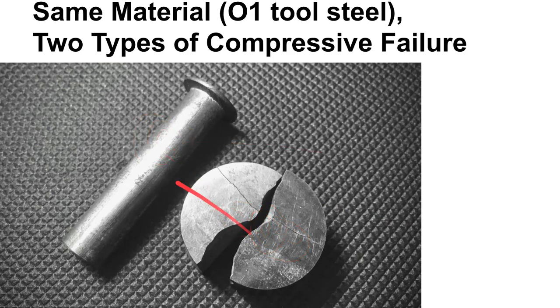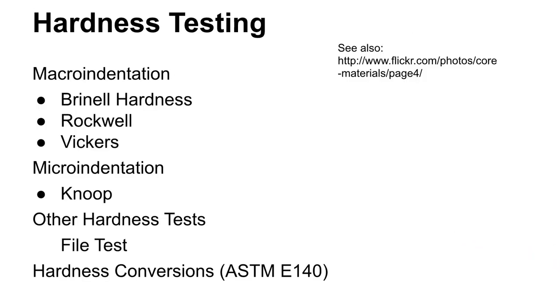This is hard and this is soft. That's a big trade-off. All right, so maybe that sets us up to talk about hardness testing. Because hardness testing is a good way to evaluate what has happened to that yield point without actually destroying the part by doing a stress strain or tensile test on it.